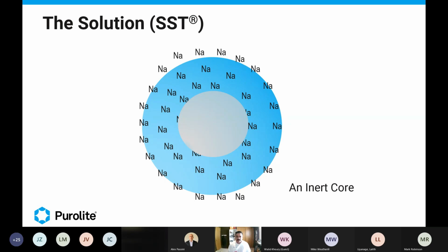Not only is SST less fouling, it also uses less chemical when you're doing a regen, because you're not drawing that chemical into the center of the resin bead. It's just on the outside. The other benefit is we've seen huge reductions in fast rinse times on systems, especially some of the larger systems out there. Fast rinse is the last step in your regen procedure, to flush off the remainder of that chemical that might be left. If it's all stuck in the middle of those tiny little beads, it takes a long time to flush out, whereas if it's just on the outside, it flushes off really quickly. We've seen as much as a 50% reduction in rinse down times, a 25% reduction in chemical usage, and better quality water overall.